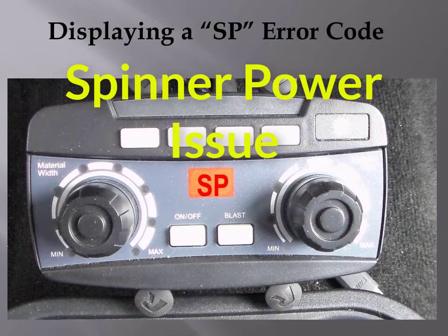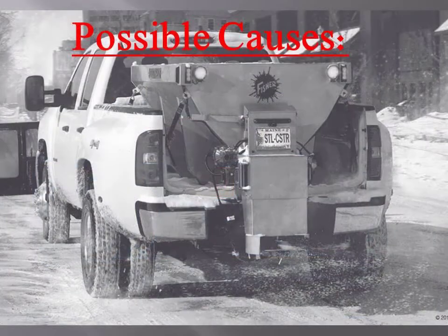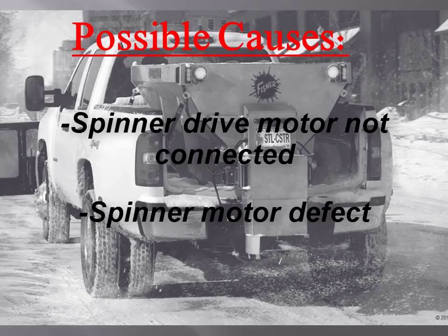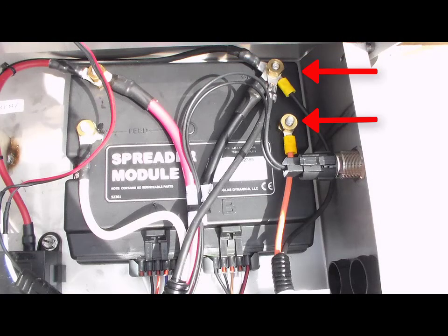SP indicates a spinner power issue or no spinner motor connected. The possible causes are that the spinner drive motor is not connected or there is a possible motor defect. Verify that all the harness connections are tight and free of corrosion.